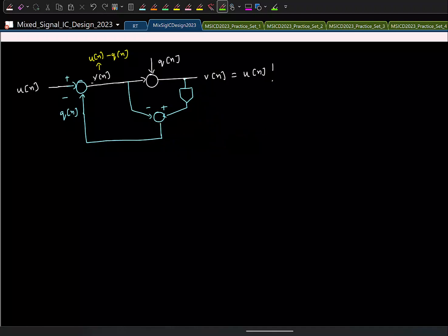In pipeline ADC, we decided to subtract the quantization noise at the output side. Output was digital, so this had to be digitized further and then corrected. And here we put a gain to have full scale. So now I don't need a second ADC. I'm reusing the same ADC and doing it, right? And it looks like conceptually this is fine, right? So what is the catch?